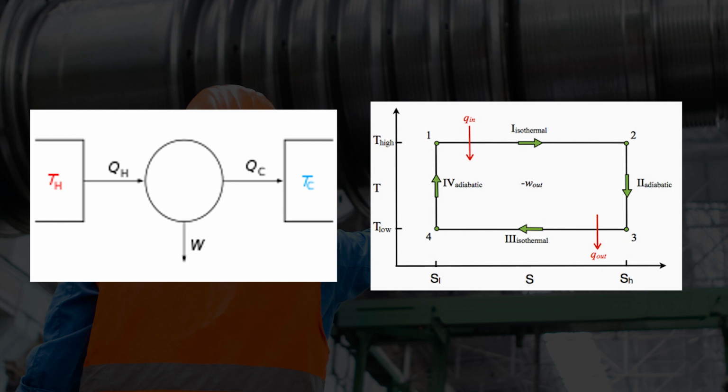In the same slide we are able to see the TS diagram. T shows the temperature in the vertical direction and S shows the entropy in the horizontal direction. So, here a rectangular kind of shape is presented, which shows the work done in the Carnot cycle.